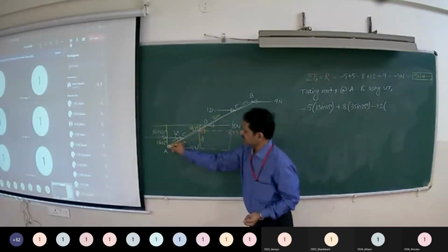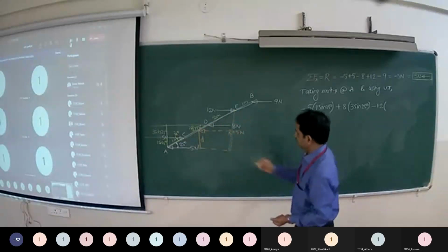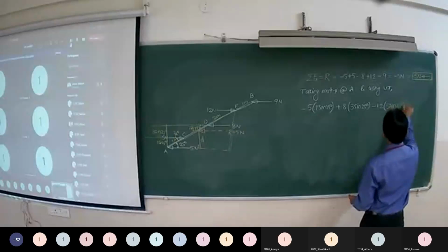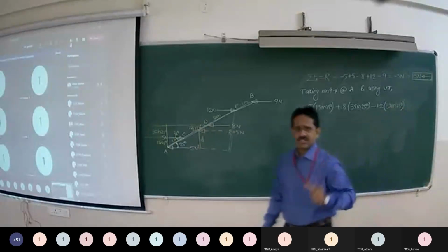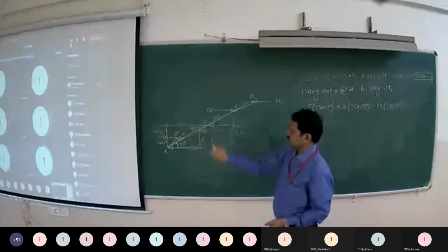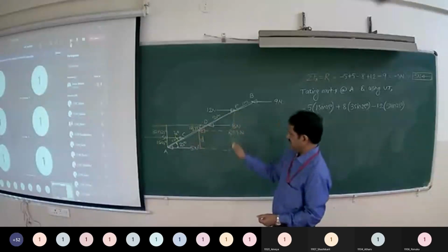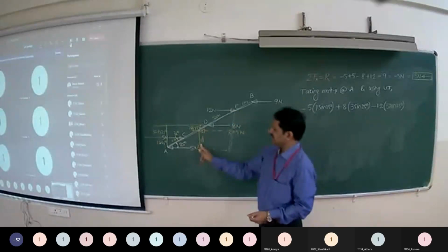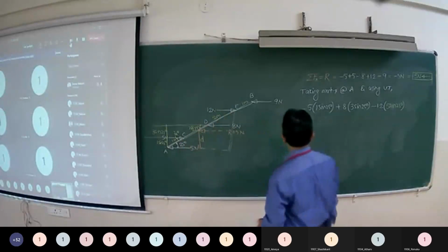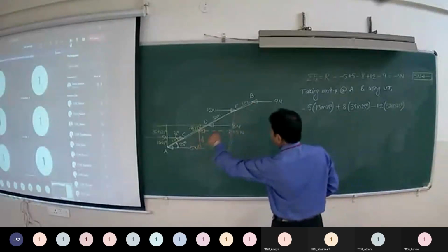Now see this total distance, 1 plus 2 plus 2, 5 meters, so the opposite side is 5 sine 25. Are you following me or not? For these horizontal forces, the vertical distances are perpendicular. You know this 25 degrees, so the vertical distance is the opposite to 25, which will be the sine of this hypotenuse. Yes. Now the moment of this 9 Newton about A.